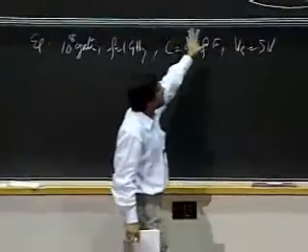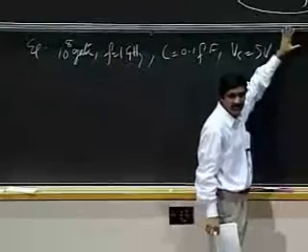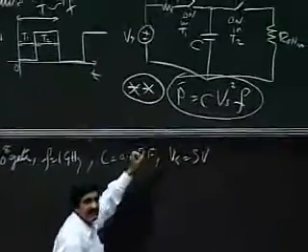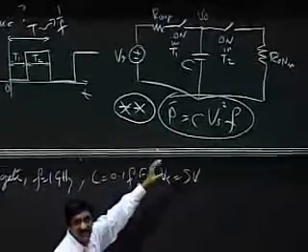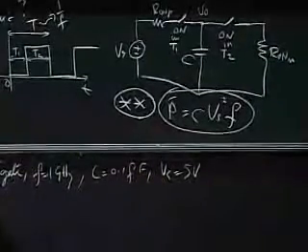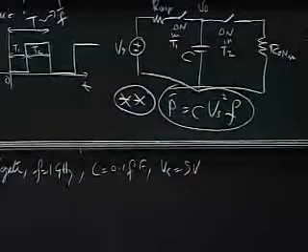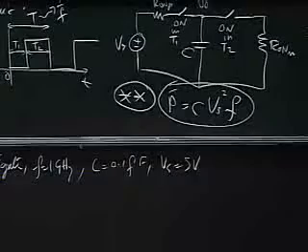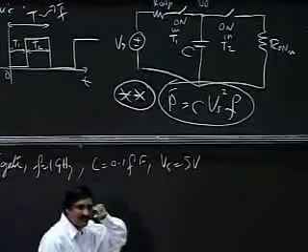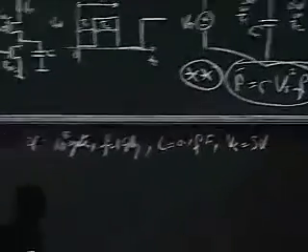Why is it that I don't have any resistance component here? Because the power consumed by the circuit is independent of those resistances, provided T1 and T2 are much longer than the two time constants, R on P C and R on N C. So I don't have RL in my equation anymore. I don't have any standby power.